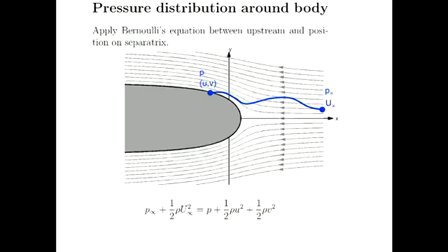So in this sketch, I'm considering a point on the surface of that half-Rankine model. I can rearrange Bernoulli's equation to get an expression for p minus p infinity, which is the difference between the pressure on the surface of my vehicle and ambient pressure p infinity. And it's just a function of those three velocities: that oncoming free stream velocity u infinity and the velocity components at the surface of that half-Rankine body.